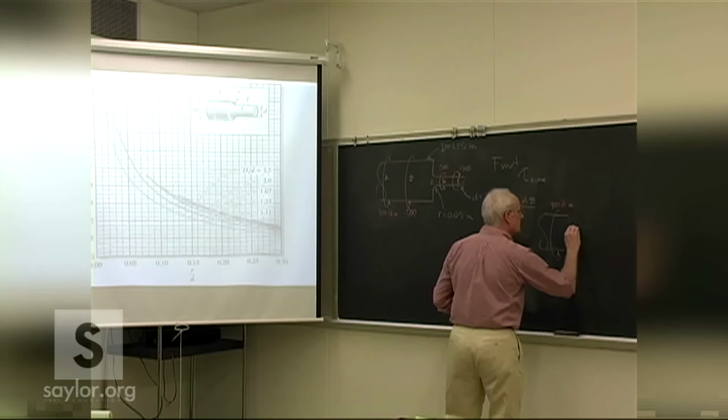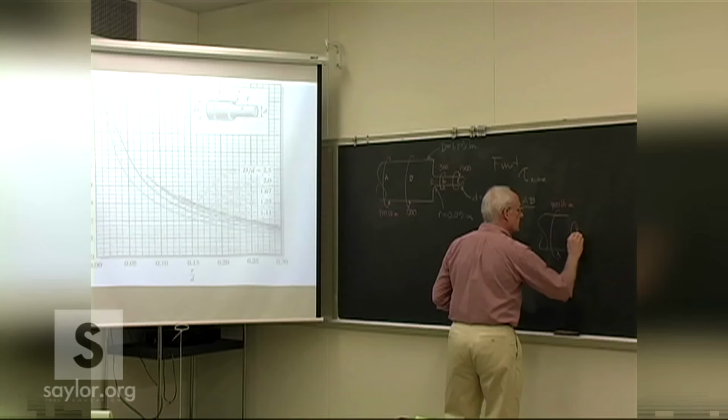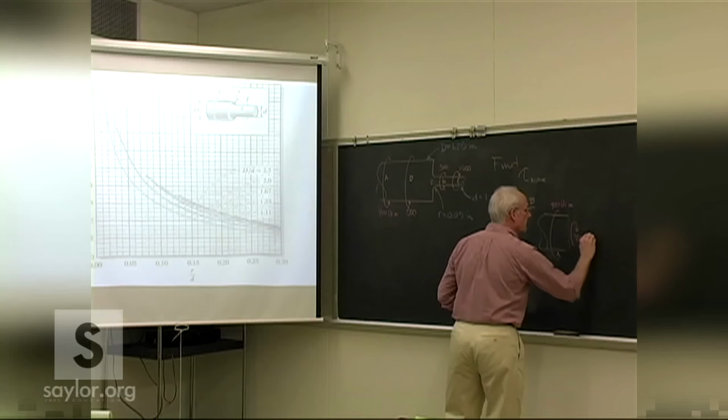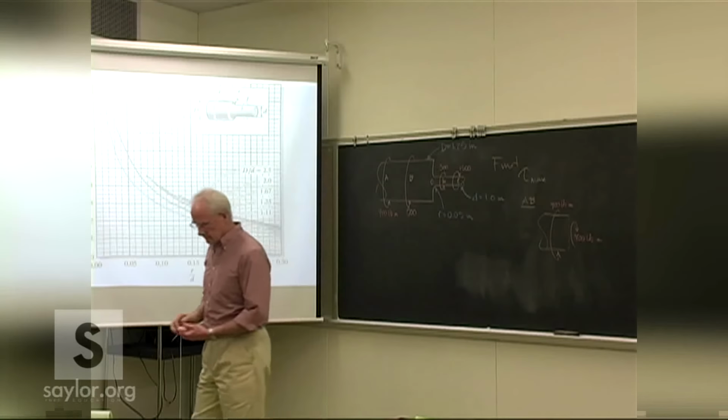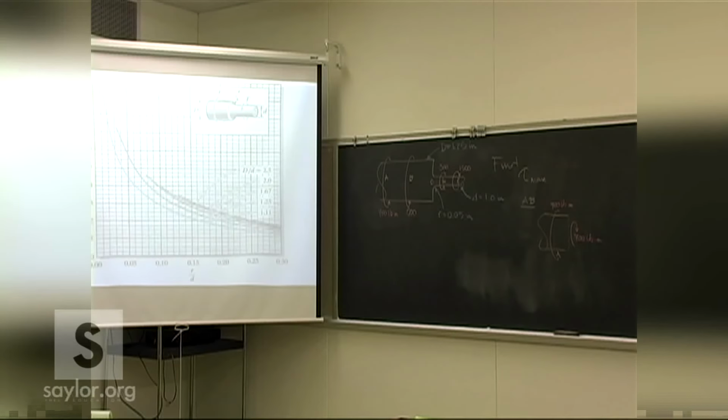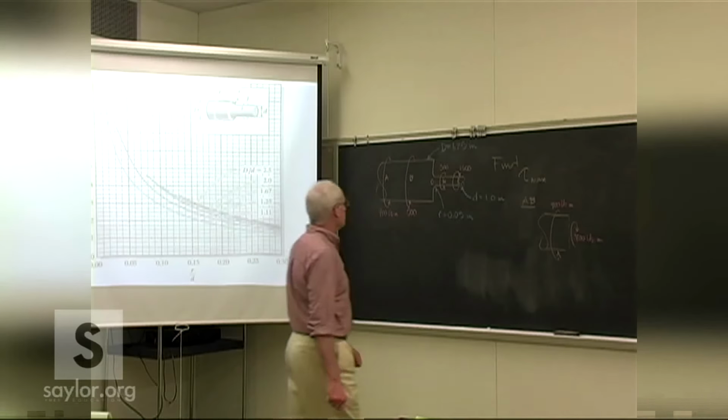So there must be an internal torsion then of, well, the very same. So you need to do that for each of the sections to find out what the internal torsion loads are, and then figure out where the area is to worry about.